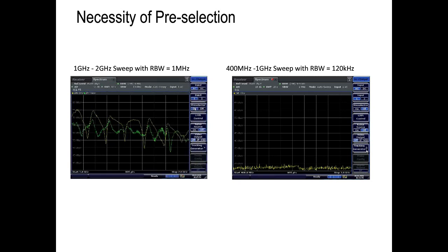And while the video is running here, let's talk about applications or where this is important. Obviously pre-selection is important anywhere that you want high confidence in your measurements that you're not getting the wrong results via overload. If you know what you're doing with the spectrum analyzer, you can increase the attenuation, but often it could be misleading. You have to really know what you're doing.